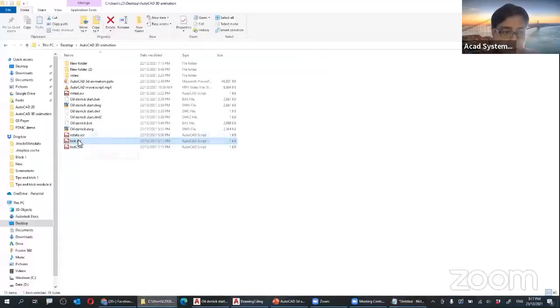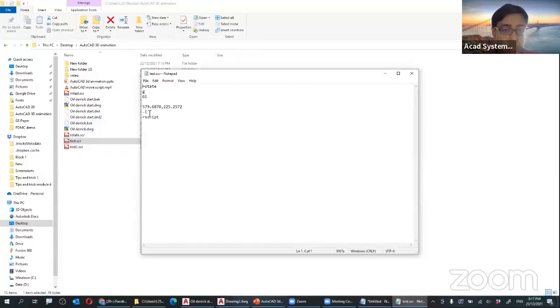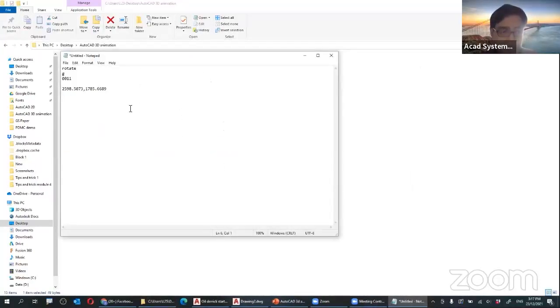So moving to the next one, if I open again, the next thing that we need is the speed of this rotation. In this case, I only put -1, right? You can put negative or positive. Negative will make your movement rotate clockwise, but if you want counterclockwise, you can just leave it as positive. So let's say I'm just going to put 1 degree and press another enter.